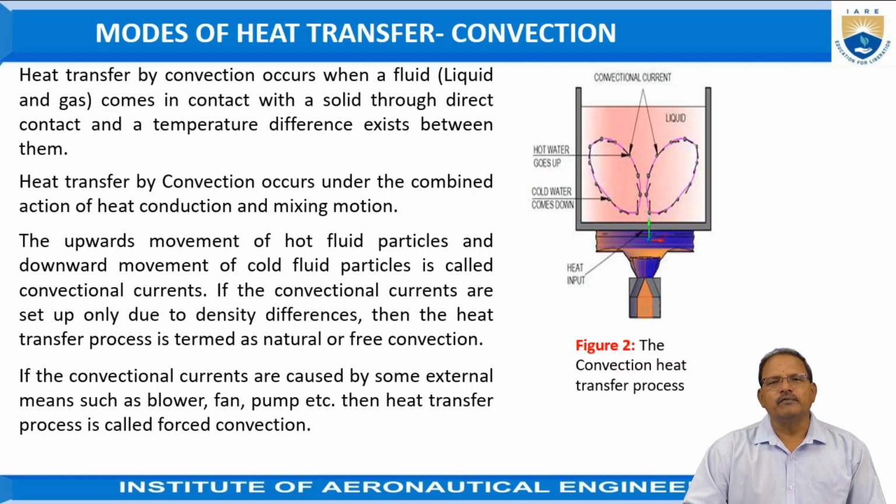As the heat energy flows from the solid body to the liquid, the liquid in contact with the bottom surface gets heated and flows in the upward direction, because its density decreases. The liquid at the upper surface, because of its higher density, moves in the downward direction. Hence, heat transfer takes place because of the density difference between the liquid in different regions.